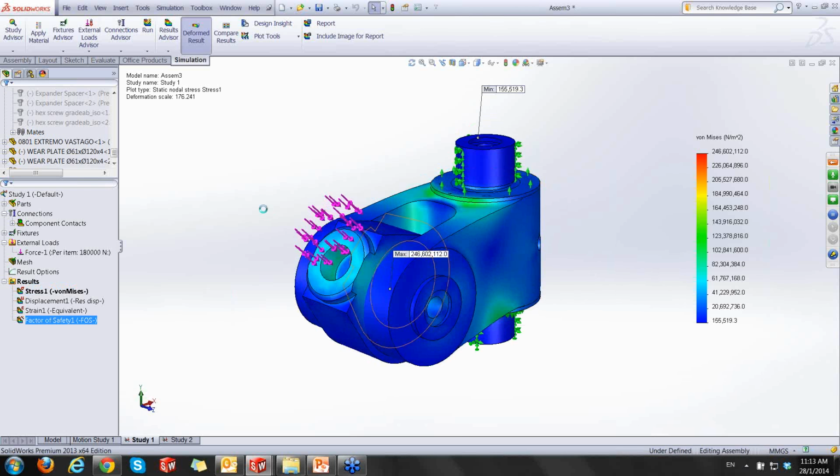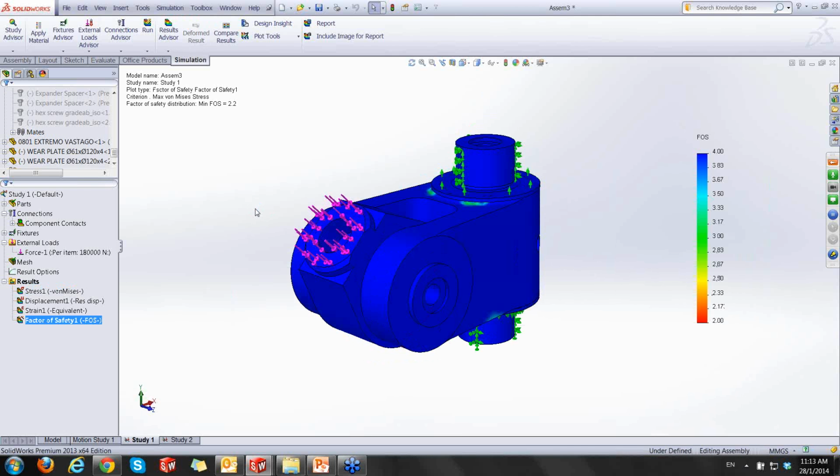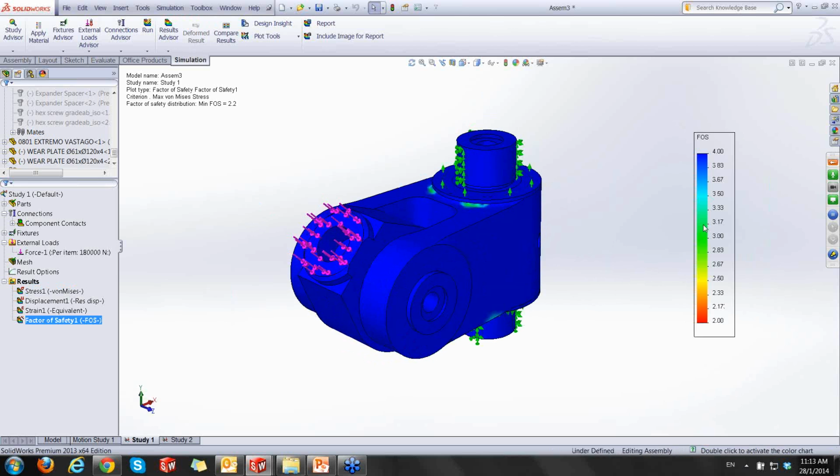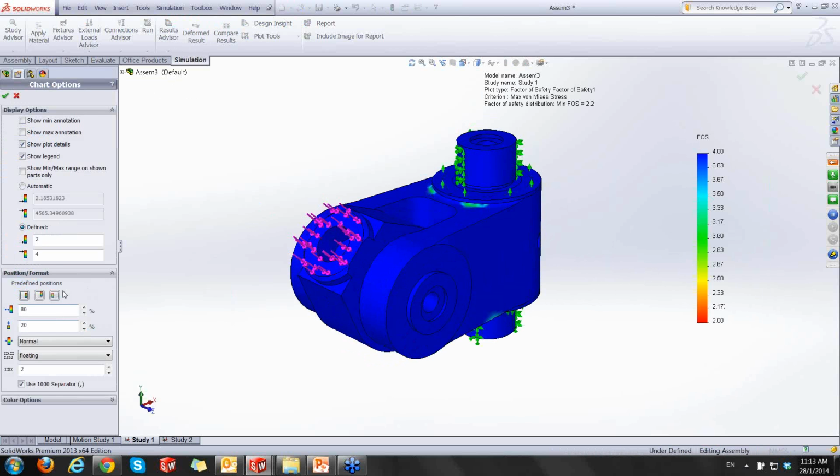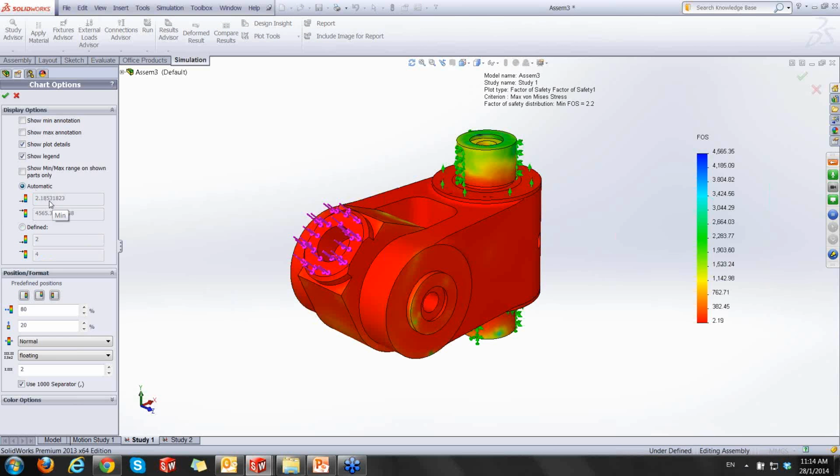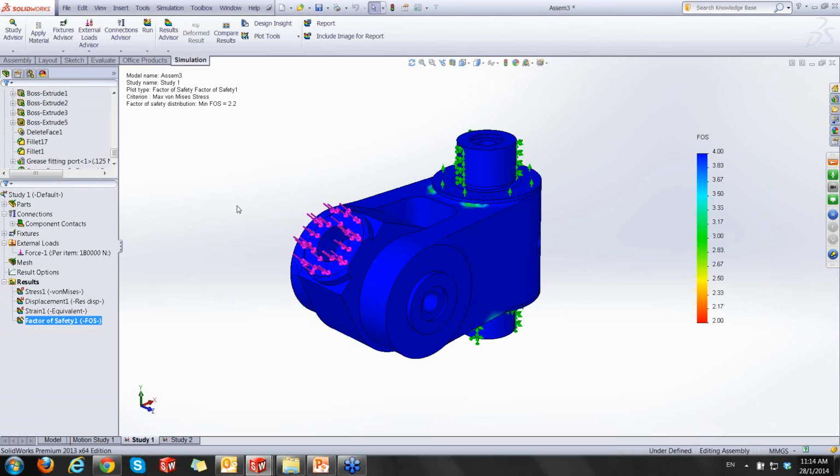Okay, so we have a new set of results from here. As you can see, even though I changed from 30 mm fillets to 20 mm fillets, the minimum factor of safety just reduced a little bit from the previous design. So it gives us more options. As a designer, from here, you get better visualizations of the design, and you can make a lot of assumptions and changes to reduce the weight while the design can still withstand the current conditions.